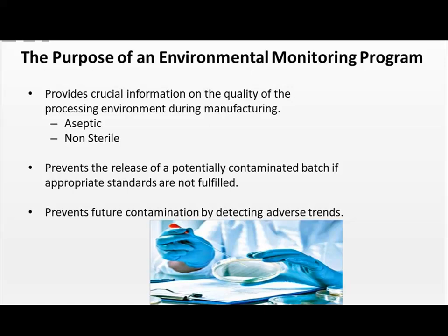It also prevents the release of potentially contaminated batches if we're not meeting specifications, because during the monitoring we are taking samples. You'll see the quality control analyst monitoring the environment and taking samples. They may be taking in-process samples of the product. They will also be taking surface samples, air samples, particulate counts, and even samples of personnel as they're coming in and out of the core or the manufacturing suite.